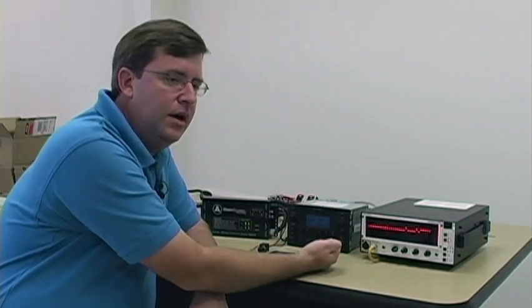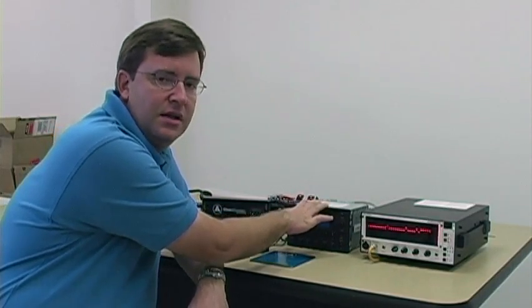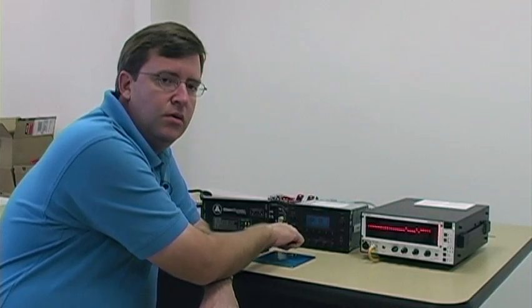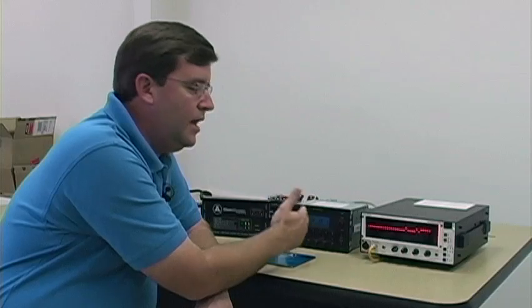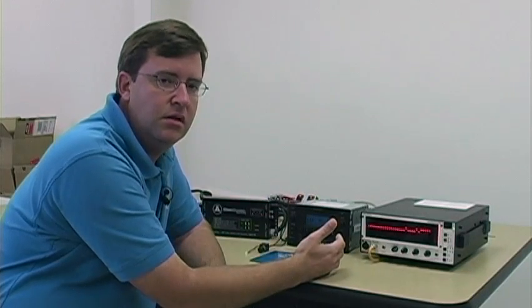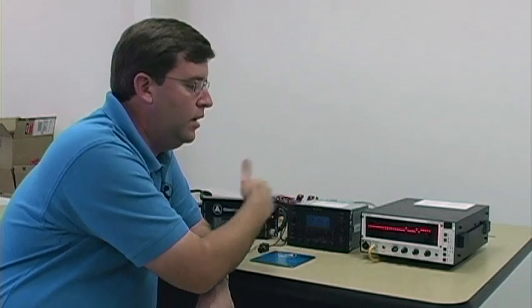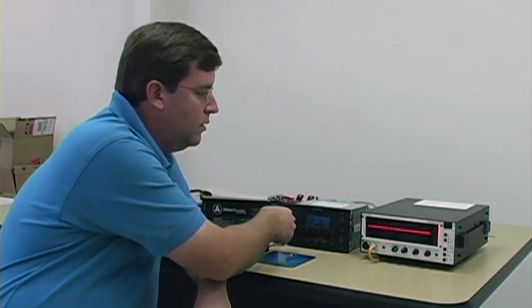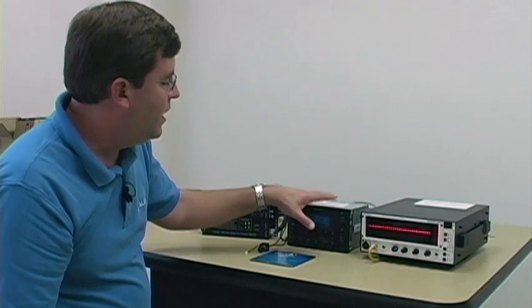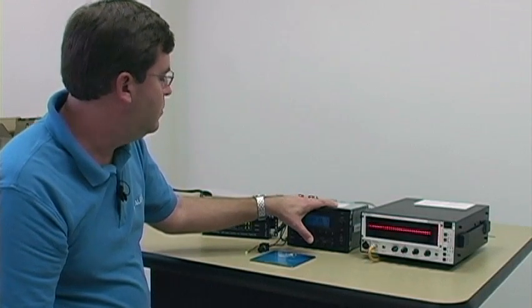You don't want to go all the way up because we want to make sure this radio is not clipping. And you don't want to go too low on the OEM volume because then we might not have enough signal to get a clean result on the other end. The more signal we have going into the CleanSweep, the better our result is going to be. Okay, so we've established our 3/4 volume level at this point.